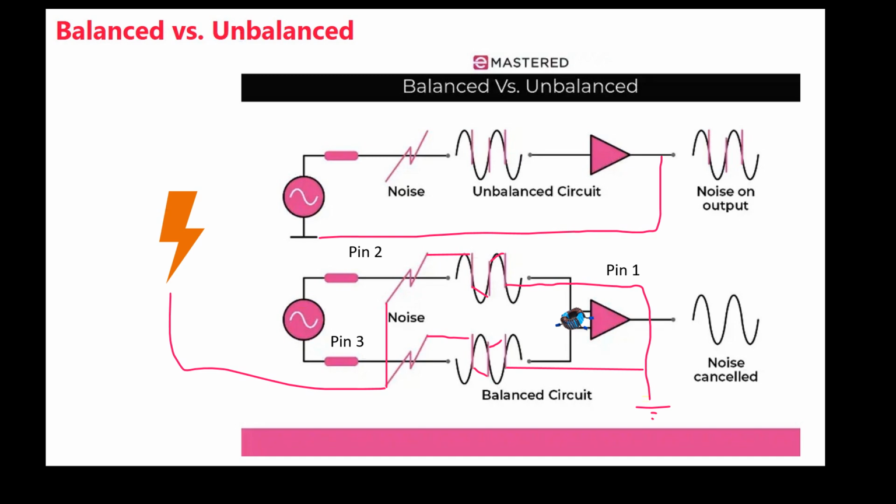And what it's leaving out is that the noise, although it's in the two main lines, pins 2 and 3, in the mic line, a transformer, a choke transformer, ignores it. It's hard to put into language, but it doesn't allow this interference to flow through.